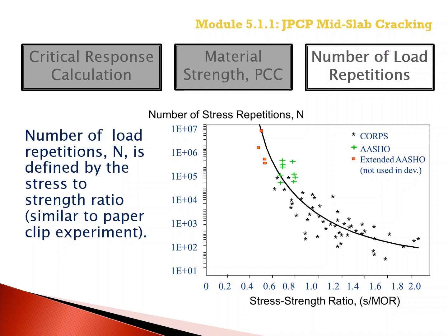However, most of the PCC fatigue models are now based on the stress to strength ratio, as shown in the graph displayed in the slide. The stress to strength ratio was found to normalize the difference between different PCC mixtures with different flexural strength or modulus of rupture values.